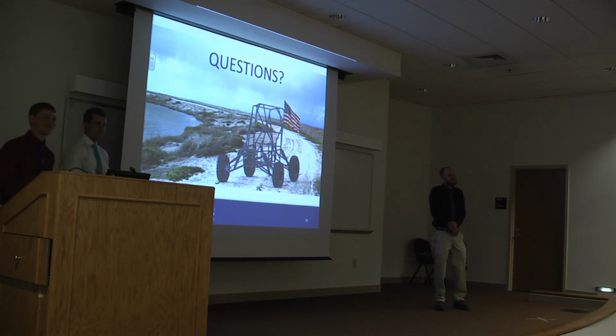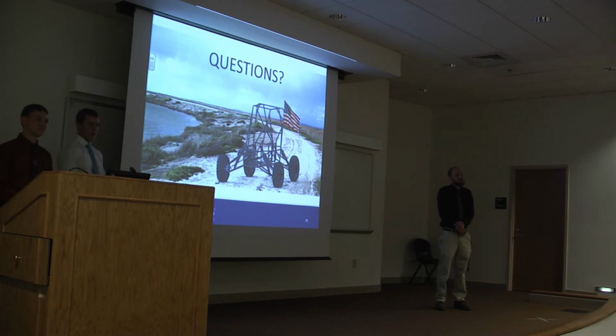It was a good job on the presentation, but my question was on the 3-inch lift you got. What did that do to stability of the vehicle on turns and stuff? Did that make it harder to control the turning? Clearly, that will increase the roll of the body, but how we mitigated this was, again, with the unequal control arm lengths. That does offset the increased body roll, so that's how we were able to mitigate that risk.